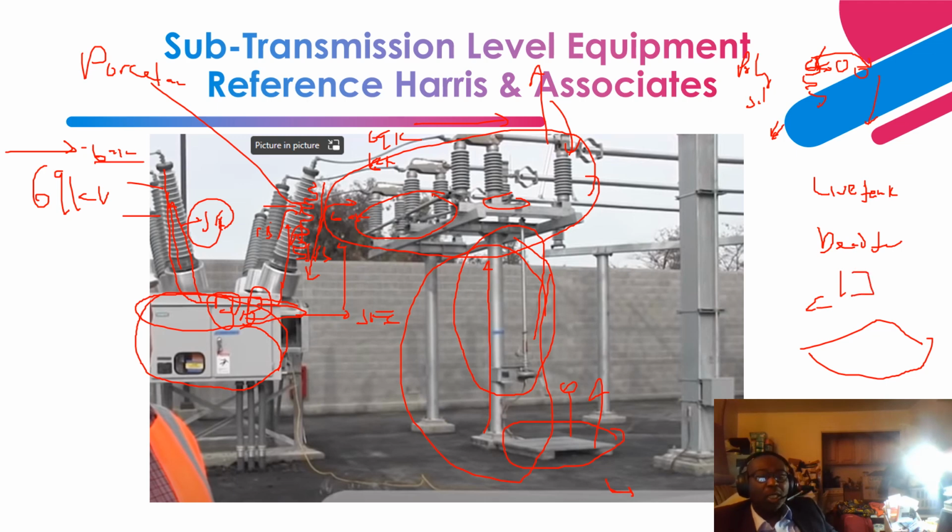Okay, so the ground cable is bonded to this equipment, right? Then to the equipment, you have a ground lead that comes in here and goes through a ground rod that is connected and welded to this ground mat. So this ground mat is in a grid formation,